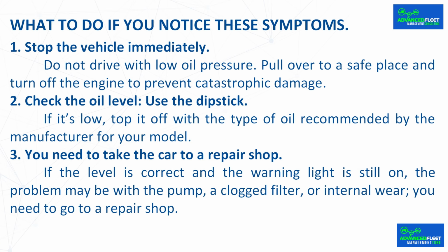What to do if you notice these symptoms? Stop the vehicle immediately. Do not drive with low oil pressure. Pull over to a safe place and turn off the engine to prevent catastrophic damage. Check the oil level. Use the dipstick. If it's low, top it off with the type of oil recommended by the manufacturer for your model. You need to take the car to a repair shop.